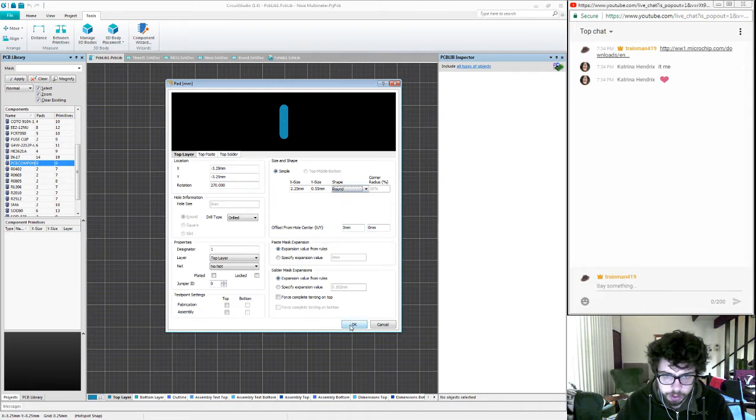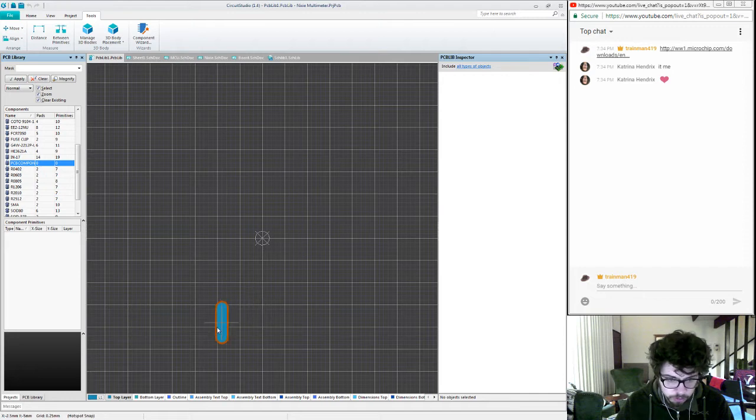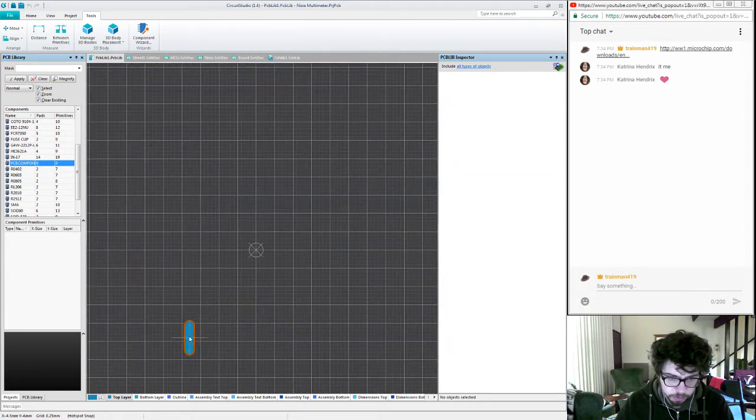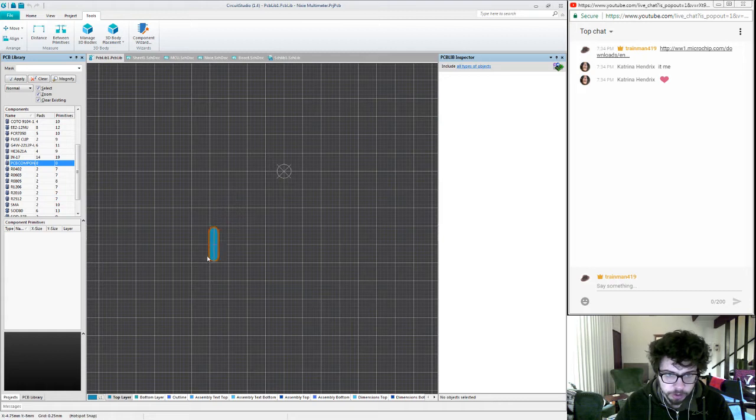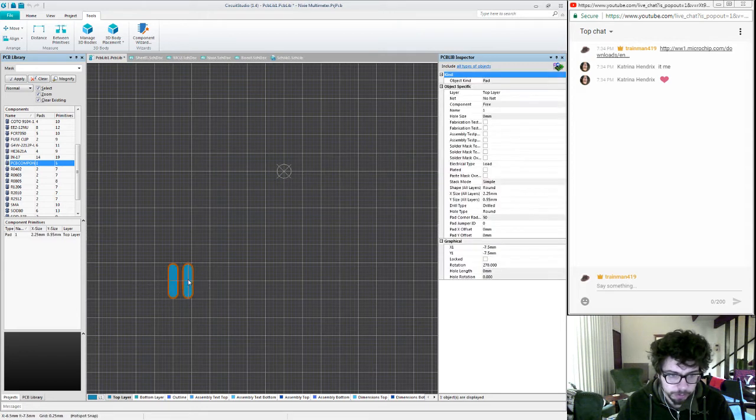I'll do fully rounded pads. The square corners on some of the older pad layouts create a stress point that can be problematic for a lot of parts. It can be the first point, basically that stress point at that corner, where your pad will start to peel off the board, or where you'll get a crack that can form in the silk screen, or a bunch of other fairly subtle but really annoying problems if they actually happen.